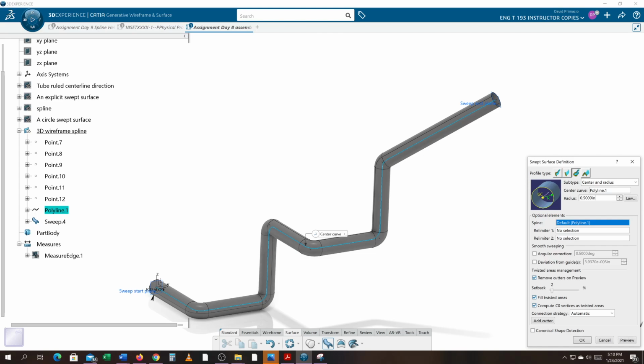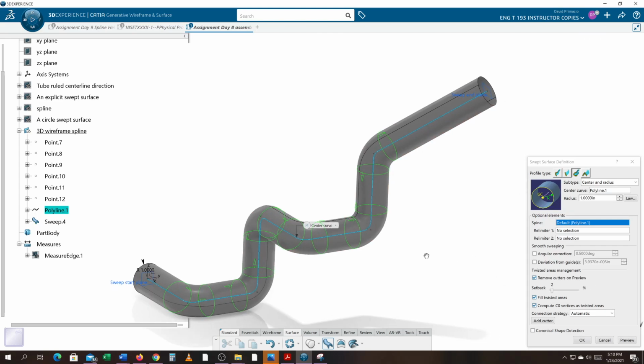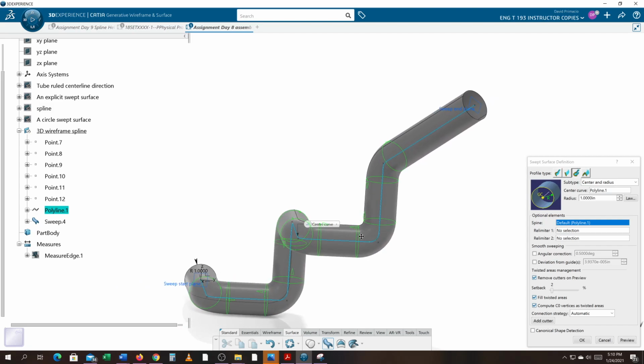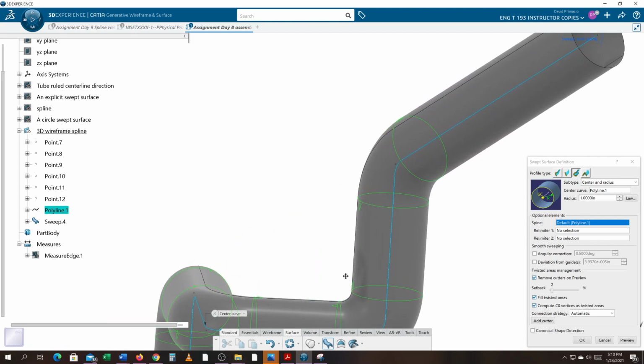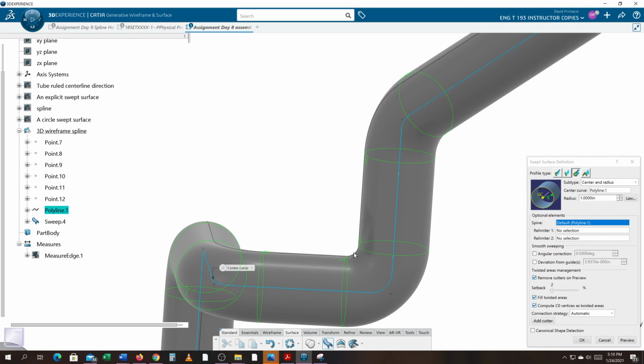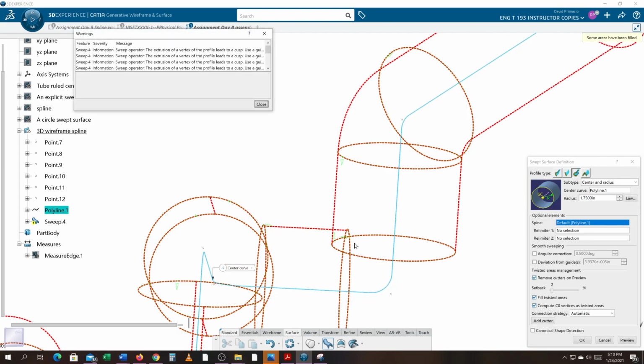So what would happen if I went with a 1 inch radius? Okay, at some point, see these green circles? They're going to zero themselves out and they're going to hit. If I go to 1.75 and hit preview, too big. They're crisscrossing, outer normal, inverted error.